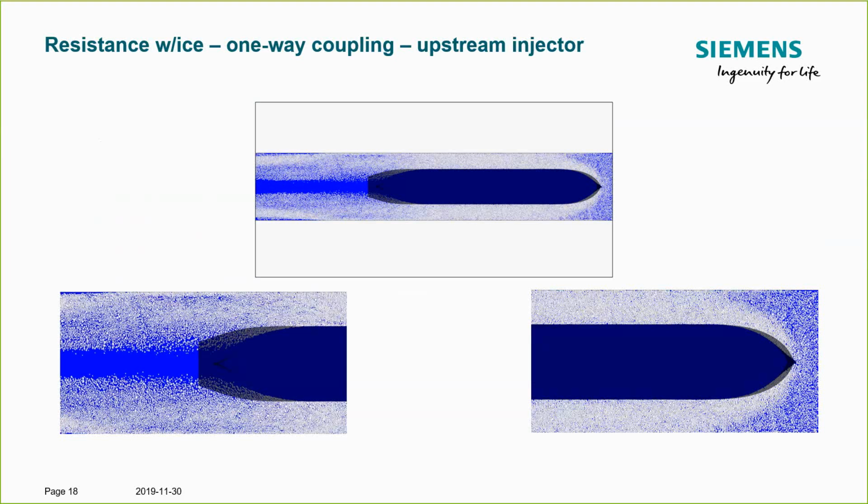As they encounter a reduced cross-section, starting at the foreshoulder of the tanker, they will conglomerate more, and there will be a higher packing density because the cross-section of the flow is lower. Then as they go downstream past the aft shoulder, this will relax a little bit, and they will build up the wake that we see here.